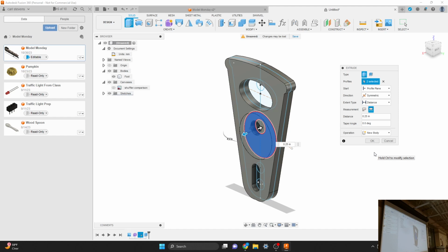Yeah, it looks like we're missing our line didn't connect. Go back to the axle and edit the sketch. There's gotta be a cam in the middle of that axle. Say edit sketch, and then if you go up and grab your tangent constraint there, pick your line, pick the circle.